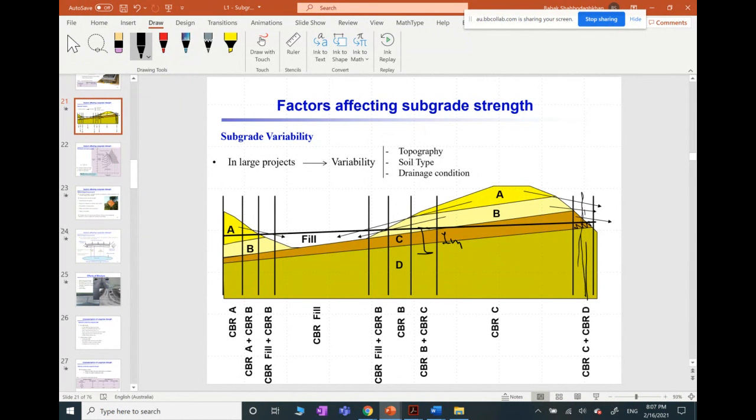Is empirical pavement design more widely used than mechanistic design in the project? Not necessarily. Empirical pavement design is widely used for most of the roads, but there are still many important roads that you cannot design just based on those empirical methods. So when, for example, you have a cemented layer, or you have an asphaltic layer at the top, you have to go through the mechanistic design method. Again, I will explain that in detail in lectures 3 and 4.